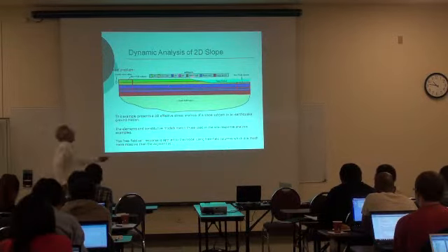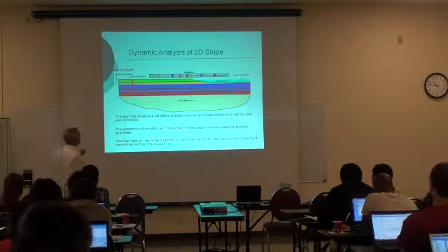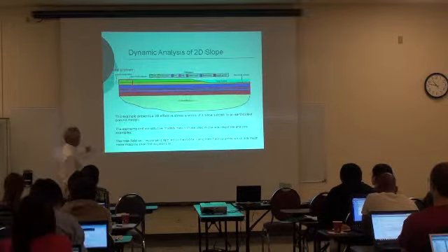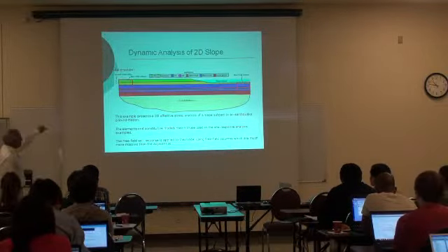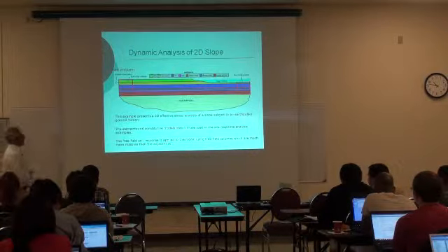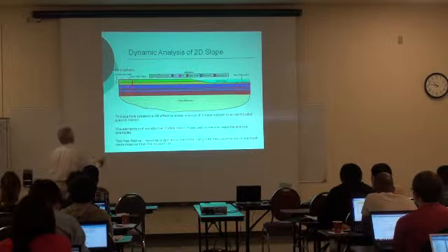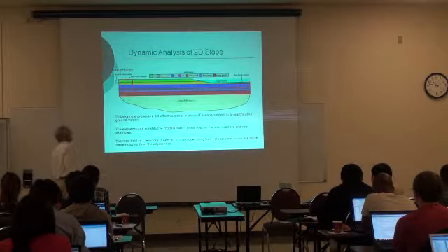So then you have to do two-dimensional elements. We have to model the boundary conditions, the compliance base. Again, you can model that using a dashpot. How to model these boundaries here on the left and the right edges? The way I've been doing that in OpenSees is to impose a free field response at both ends. How do I do that?